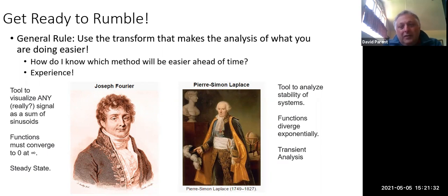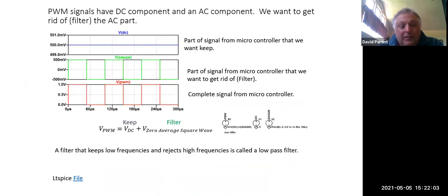And it really boils down to this: if we didn't do the Fourier analysis and the pulse width modulated DAC, you might just think, oh, set S equal to j omega, and you can do your Bode plot. And that really is kind of what happens, right? But by breaking up a signal into its sines and cosines, you can do some things that you can't do in Laplace. And one of them is this pulse width modulated DAC, which you should be familiar with by now from 110 lab.